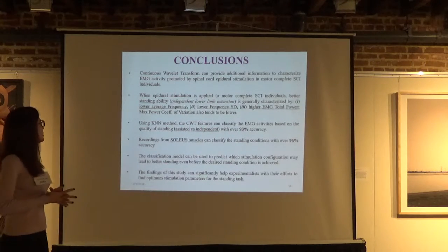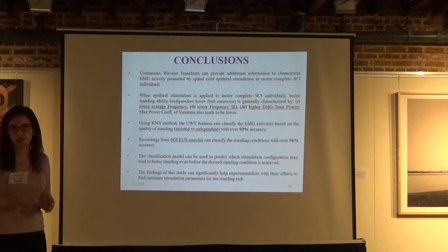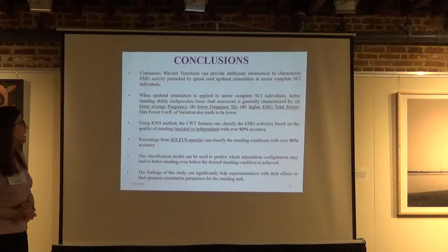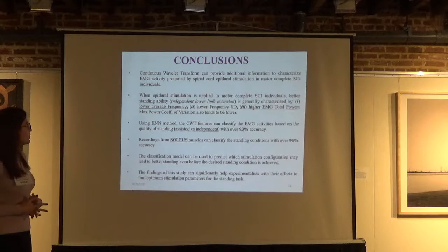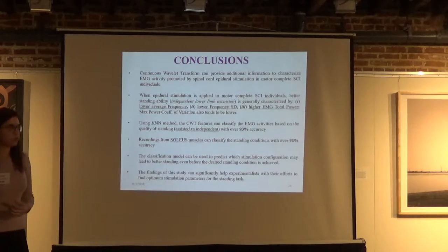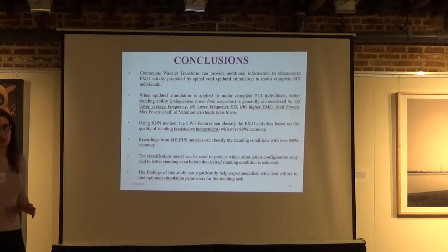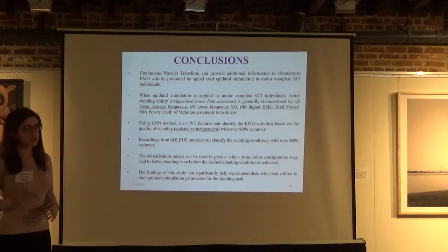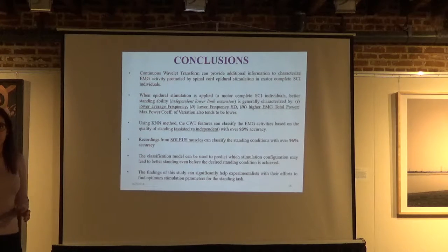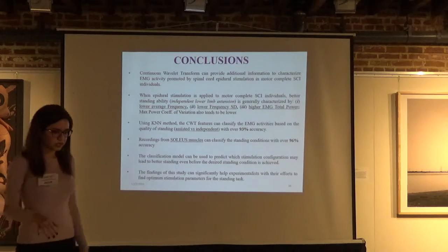So overall, what we found out is that the wavelet transform gives us additional information to FFT and STFT for a spectral analysis of the EMG signal. And we found out that with the epidural stimulation on, when the standing reaches independence, the average frequency is lower. The standard deviation of the frequency is also lower. The total power goes high, and the max power coefficient has a trend to go down.